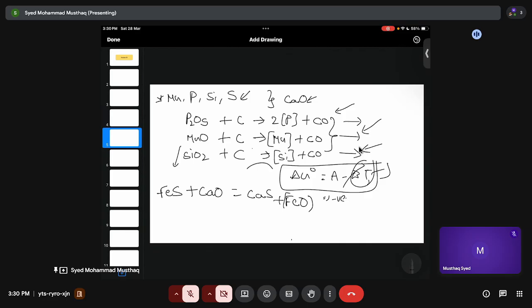Now all the phosphorus that has been present, even if you do anything, because we are maintaining very highly reducing atmospheres. We need an oxidizing atmosphere so that the phosphorus pentoxide can be taken out. And this phosphorus pentoxide is easily reduced by the carbon and picked up by your iron. So you cannot do much about that. And the same goes for manganese oxide. Manganese oxide has the same characteristics as Fe2O3 or other iron oxides that are being reduced. So again, being a basic oxide, it cannot be picked up by your basic fluxing agent, right? Basic oxide. So again that is one thing.